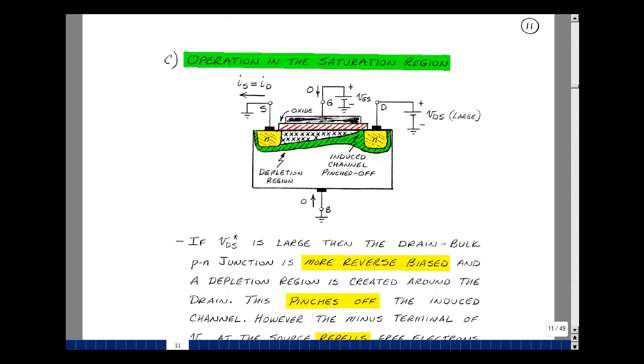Let's next take a look at the saturation region. Suppose I make the gate source voltage again 6 volts, but now I come way out into the saturation region, say maybe this is 5 volts, and then that would make the gate source voltage here 6, but now the gate to drain would be equal to 6 minus 5, or 1 volt. Voltage across this PN junction here, and it's going to be 0 minus 5. We again are reverse bias, so we're creating a depletion region.